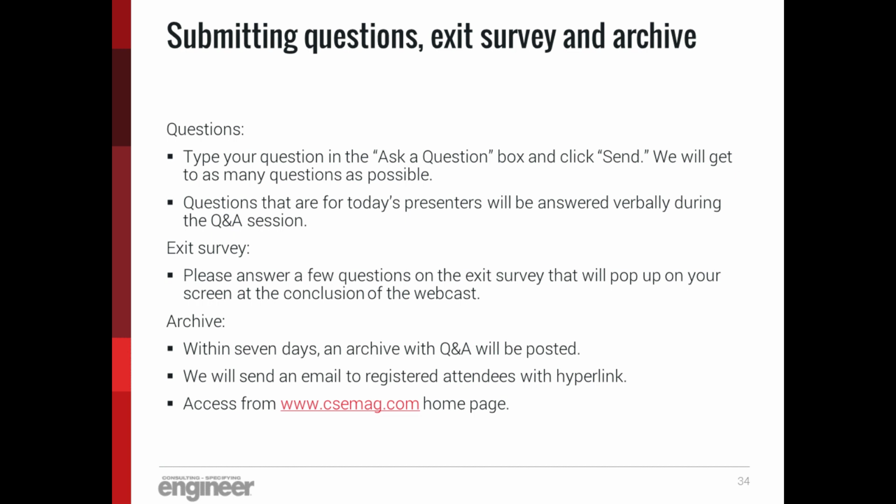Now, when we're looking on the emergency side, we're interested in knowing, do we have a ground fault? But we're not required to trip on that. Instead, we would like to get an alarm. So your LSI-G, right, your G is your ground fault. Your LSI-A is going to be your same breaker, except I'm alarming instead of providing an actual trip. And that's important because we want to know we have a problem. But if we just shut the generator off because it has a ground fault, we could actually be doing more damage than what we would if we were to try and save it.